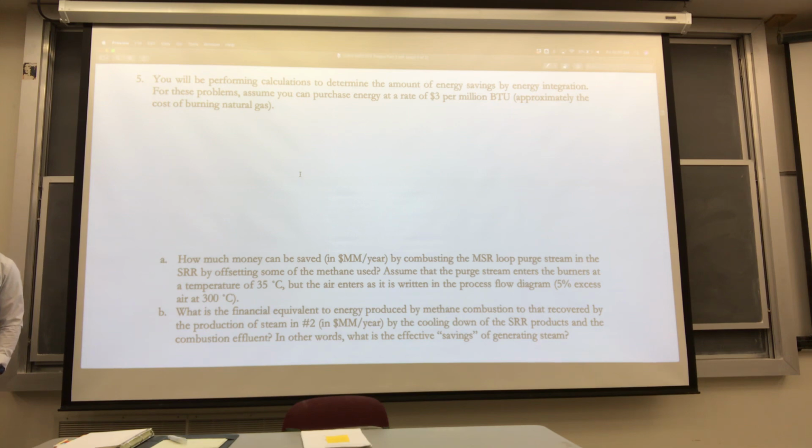So the worst time for emissions, when you start your car, your gases are cold, your catalytic converter is cold, so the catalyst doesn't work very efficiently. So when you start your car in the mornings and it's cold outside, you will be releasing a lot of organic compounds and uncombusted gasoline, potentially carbon monoxide and other hazardous material. But once your catalytic converter heats up and they get quite hot, like 1,000 degrees, then it's very efficient at finishing the combustion process. So it'll take all those COs, turn them into CO2s, take unreacted hydrocarbons, and combust them completely. So then it kind of heats itself up.